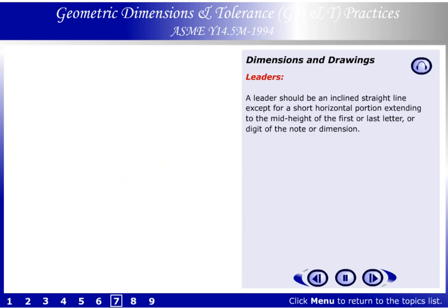Leaders. A leader should be an inclined straight line except for a short horizontal portion extending to the mid-height of the first or last letter or digit of the note or dimension.